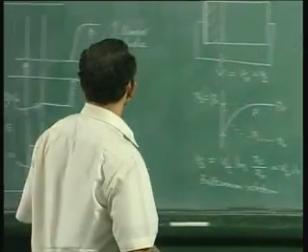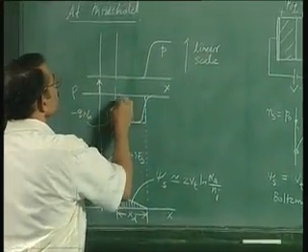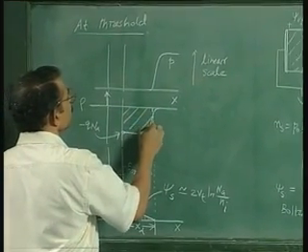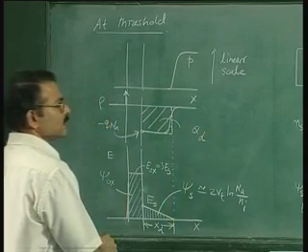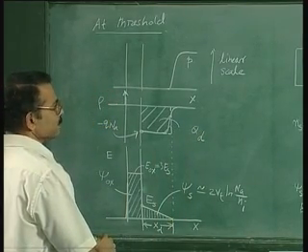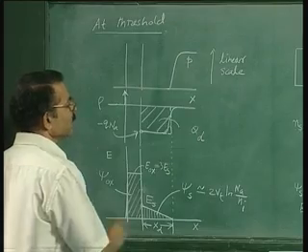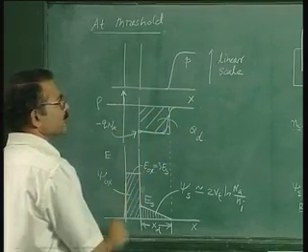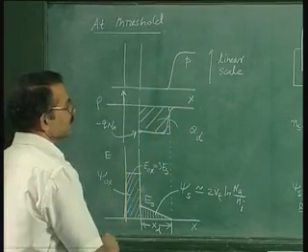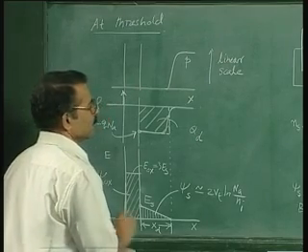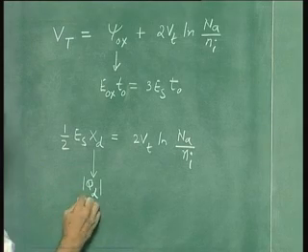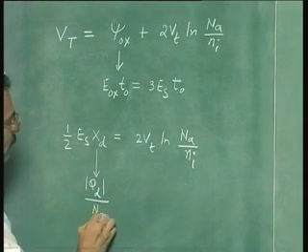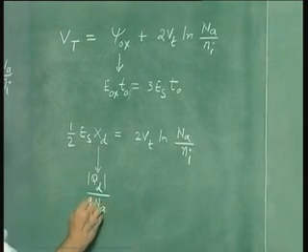Let us look at this diagram. This is the depletion charge. So Q suffix D. Of course, at threshold this also happens to be the charge in the semiconductor Qs, but that is a different issue. So now xd is QD divided by the doping multiplied by Q.